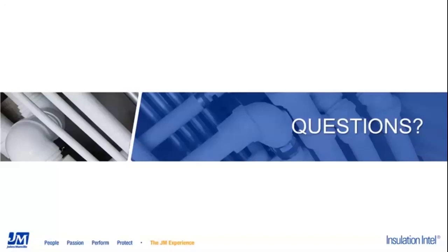I would agree with that. This is John. Again, it would depend on the application, but Polyiso has higher compressive strength and lower thermal conductivity. So if space constraint is a concern, then Polyiso might work better. But I think Meredith and Natalia covered the points.